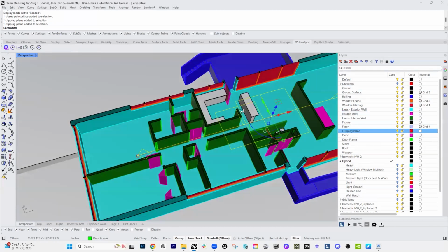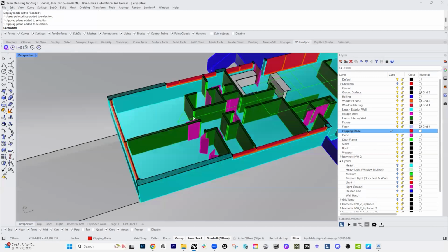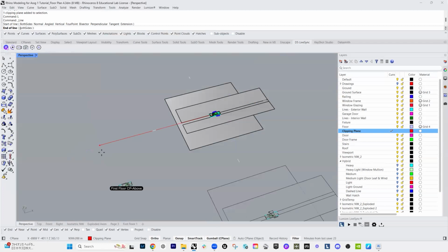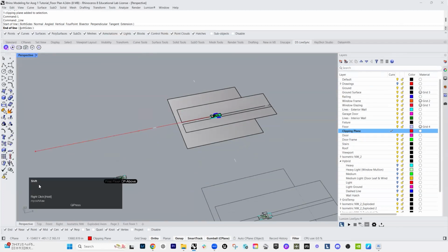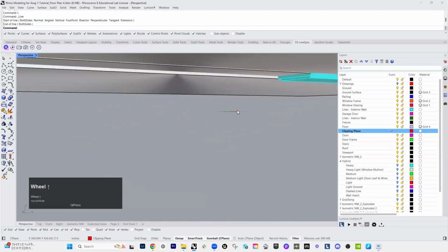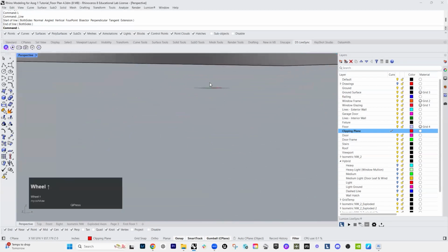Okay, now I'm just going to draw a line from this point all the way here, pressing Shift to draw a straight line. It comes out like this, and then I'm going to do the same for the line that starts from this 0, 0, 0 point on the C plane as well.